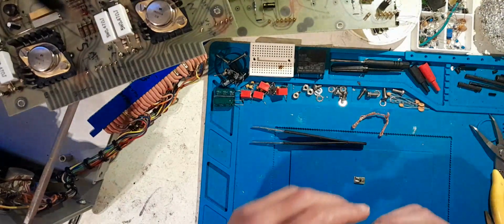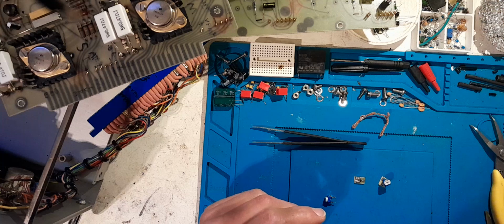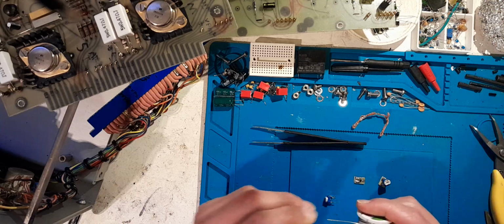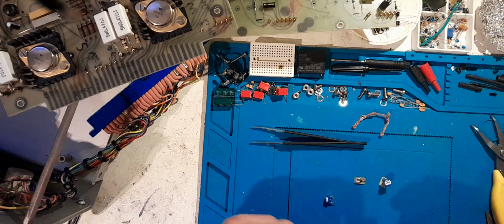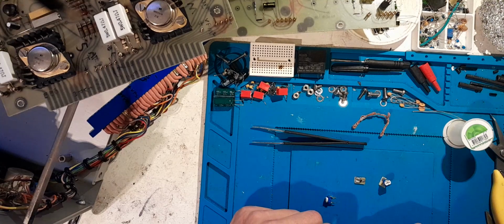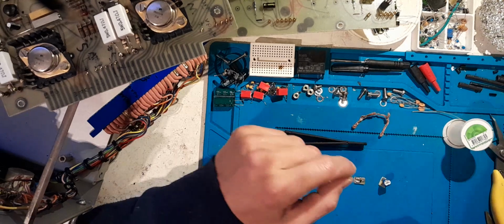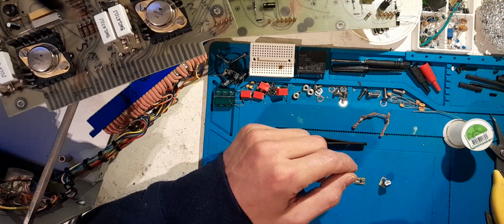And then that will just have 2 legs coming off of it, which I'll make up out of some thicker wire this time, because last time I used resistor leads and the boards were a little bit flimsy, to be honest with you. I'll use some nice thick wire, like what I had that pot and TL431 mounted on, that was just on its own without caps that we tried. So that's what I'm going to do for the top 2 references.